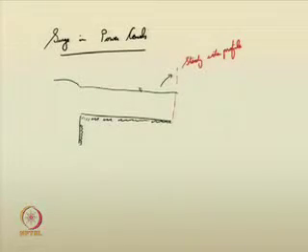Due to various factors like the closing of generators or tripping or a lot of other issues, there may be chances that the water supply has to be blocked all of a sudden to the generators or the power plants. If you stop the supply of water all of a sudden at this location, then what happens? Water starts building up, right. Also, a positive surge will be propagated into the reservoir. So, you need to take that into account.